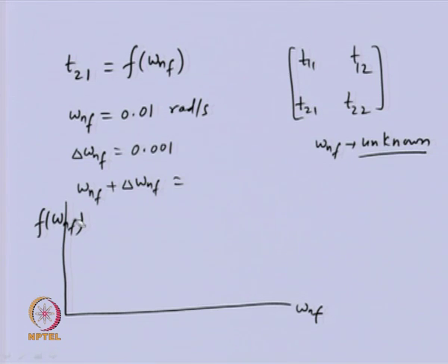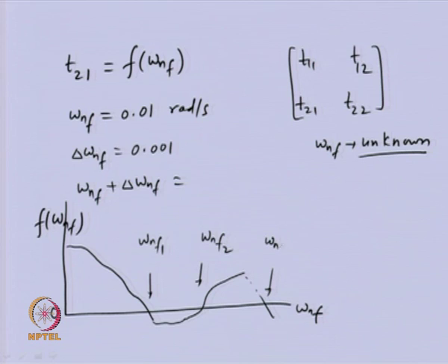So once we plot this function, we may see that it intersects the zero line of the natural frequency. That means this is one of the roots of the frequency equation, and depending upon the degree of freedom it may intersect at different places. So in general, if we have n degrees of freedom, we expect n such intersections to get the n natural frequencies of the system.